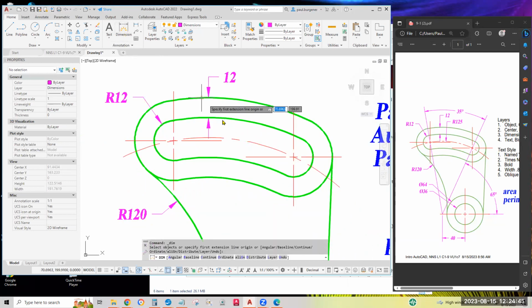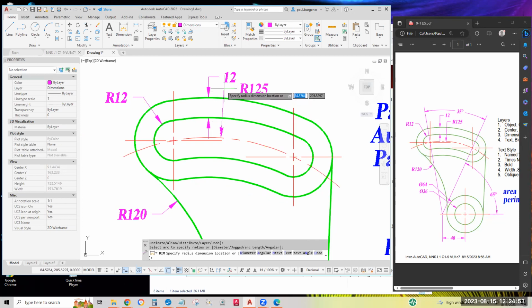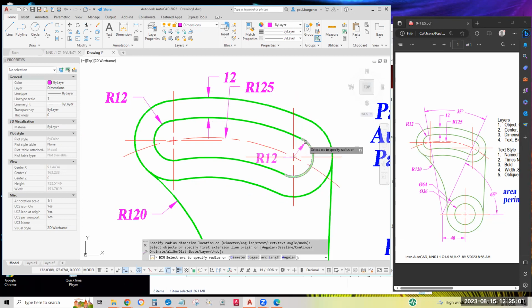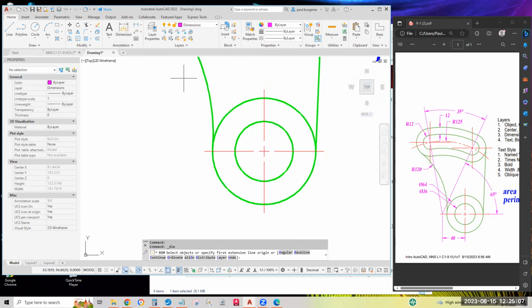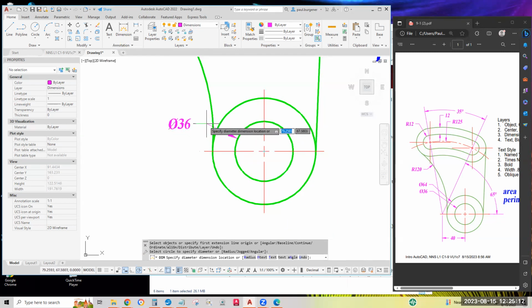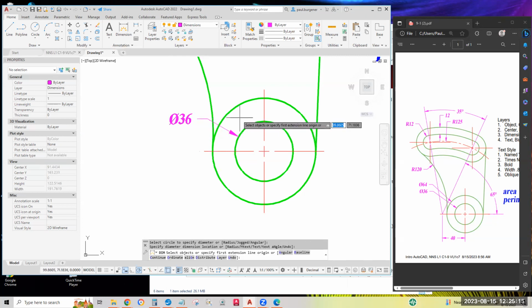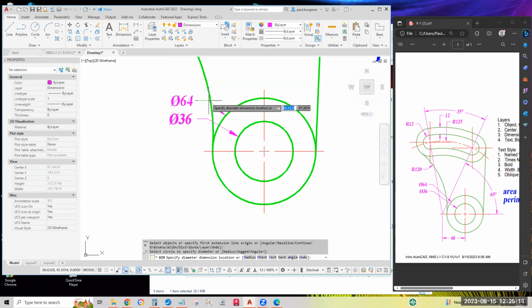Keep going here, smart dimension. Oh, snap at the red center line. Come on up. Quite like the handout. Close. And what else? These two diameters at the bottom. Let's see. We want the smaller one at the bottom. And the bigger one at the top. Looks like you can keep going and going with this icon. Don't have to hit enter, enter.